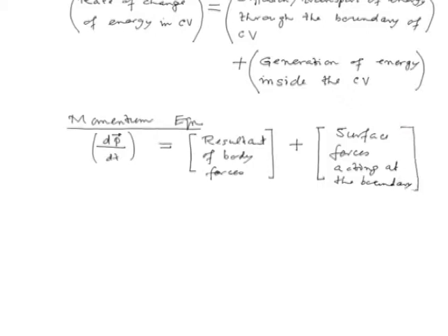Now, the second part, if you look at the surface forces, this could be thought of as diffusion of momentum, or this happens because of the transport of momentum across the control surface. So, this explains the analogy which we had invoked in this case.